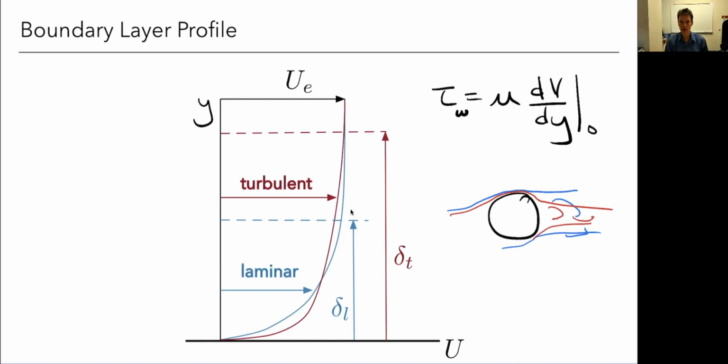So we kind of have this trade-off of the turbulence. With a turbulent boundary layer, we have more skin friction drag, but potentially we will have less profile drag. And those trade-offs depend on the shape, my application, and the flow conditions. But in general, let's say for an airplane, we would like to have laminar flow, especially near the leading edge, but we just don't want to take that too far. Maybe 30% laminar flow or so, but if we go too far, then that may limit the angles of attack we can go to.